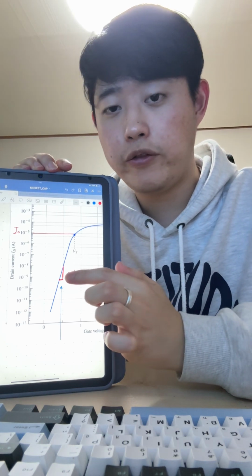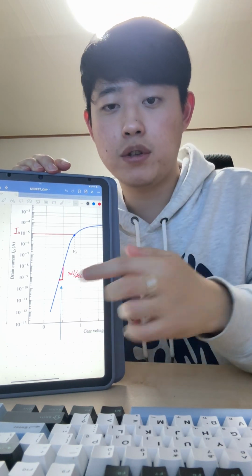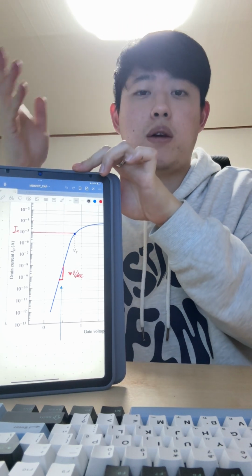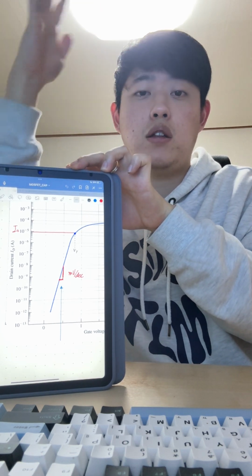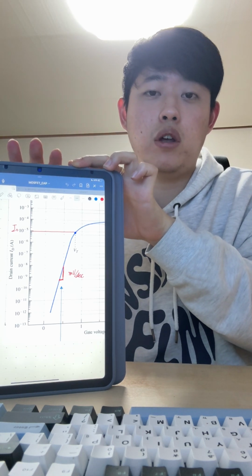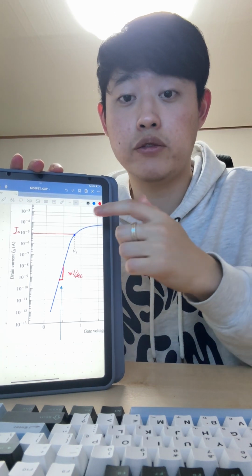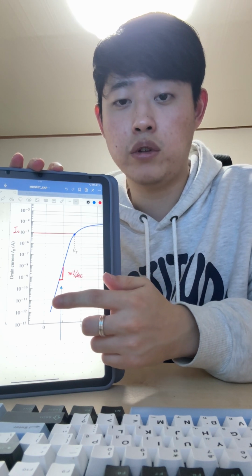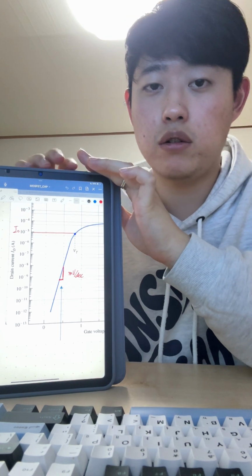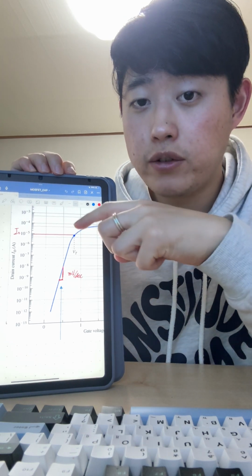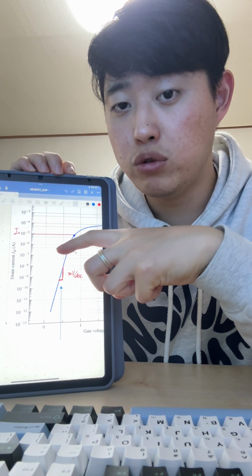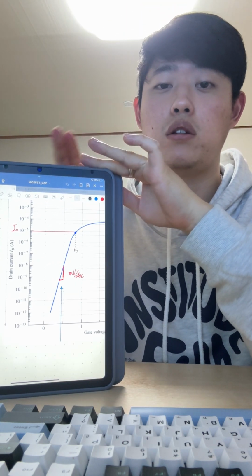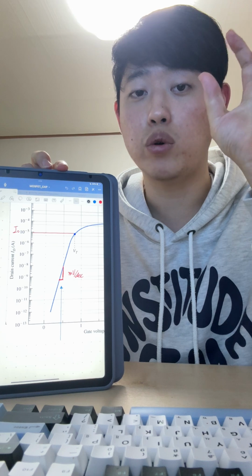So if one MOSFET has very low current, but tons of transistors spend a lot of current, there is a lot of power in standby current. So this is very useful in here or here, very important. If the slope is steeper, we can separate standby and operate mode. Okay,